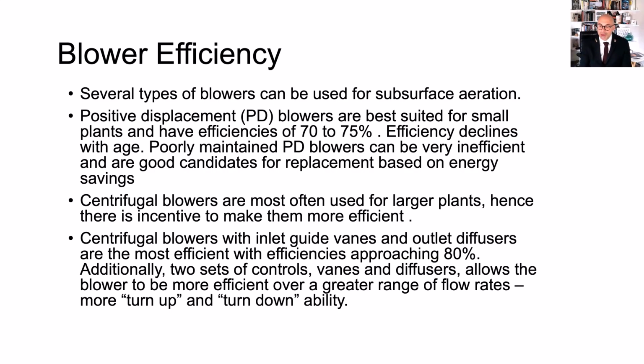But then you have blowers that are called positive displacement blowers. Those are the ones with the lobes that engage, and they always check, meaning that the blower, moving at a higher or lower speed, increases the frequency at which these packets of fluid, of air, are squeezed through the lobes and moved forward. But you don't have a very high change in airflow rate, because you can overcome variable pressures on the other side, because the lobes always check, they prevent backflow.